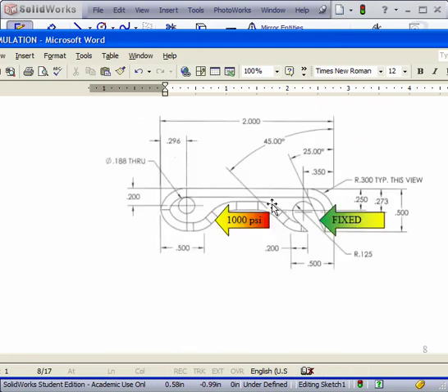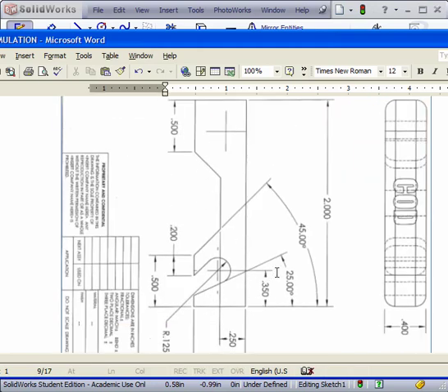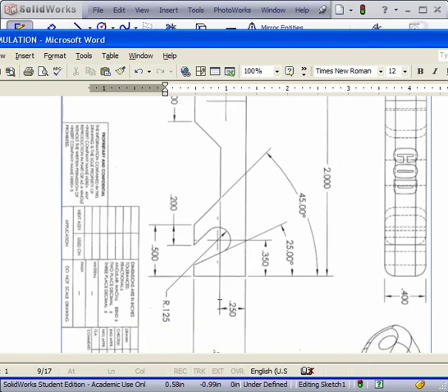Going back to the drawing, so we see that's a 1/2 inch there. We have a 45-degree angle here as well as there. 25-degree angle for the inside where it's going to contact the bottle top, and 3.5 from the center point. So we'll go ahead and continue on with that.